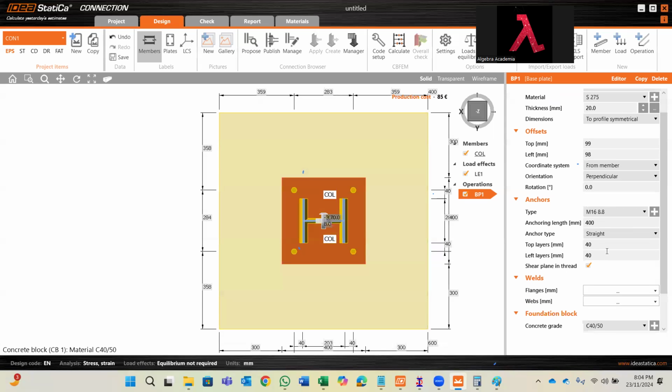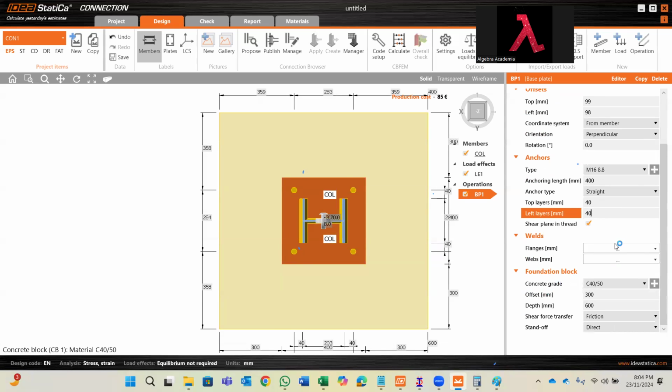And going with the weld, I'll just go for the minimum authority requirements, the weld thickness, which is 5 millimeters. Since the forces are more, I'm not going to assume something which I'm not going to fix. Okay. Anyhow, after providing all those forces and fixing all those sizes, the moment I run this design, it shows the efficiency factors, how much utilization ratio has been governed actually.